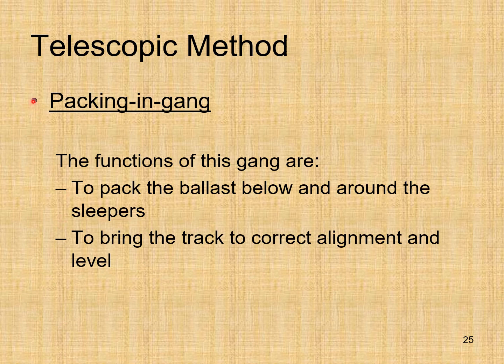Packing gang. The functions of this gang are to pack the ballast below and around the sleepers, to bring the track to correct alignment and level.